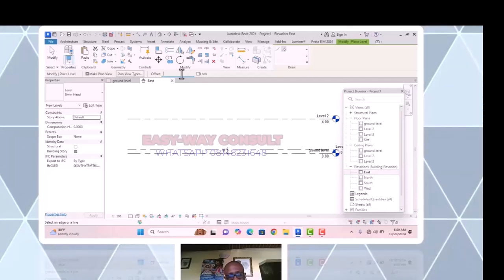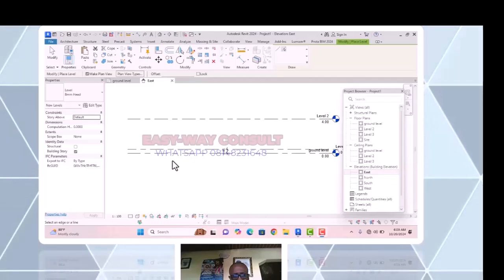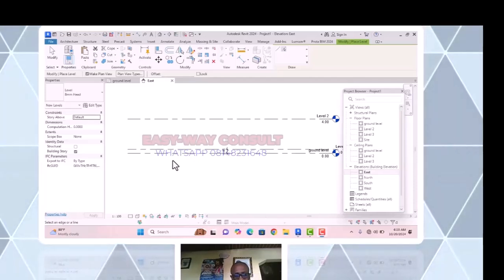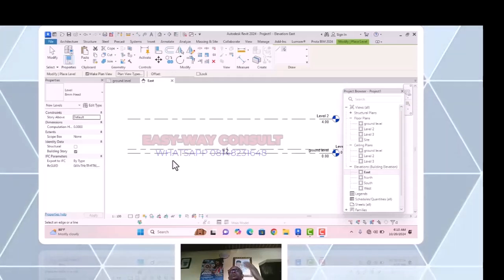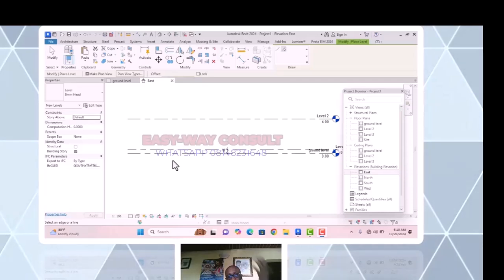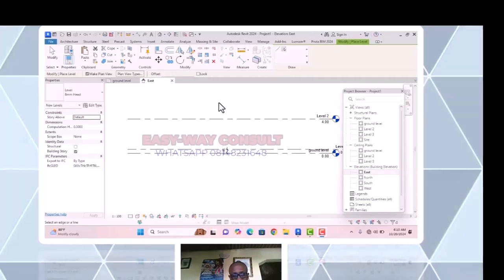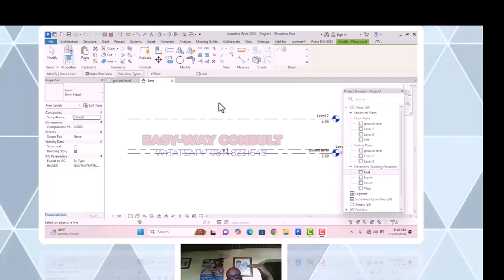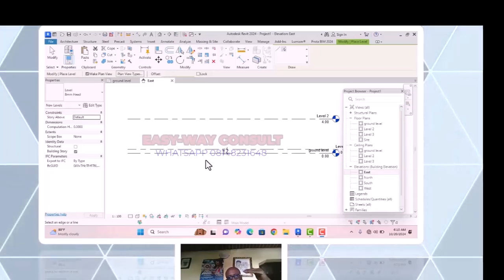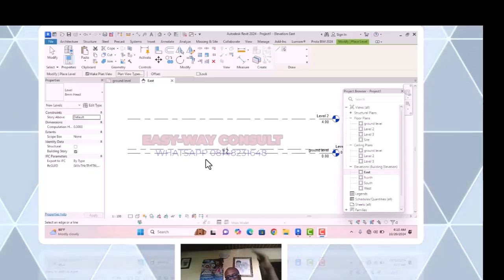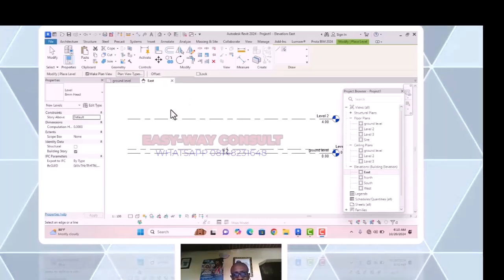Why we are putting 3.6 meter in this ground floor is because most of the time, it is going to be difficult for you to put ceiling, POP, and the rest in your building when you put 3 meters. So most of the time when it comes to deck, we make it 3.6. So 0.6 we take that of the POP and ceiling and it will automatically land the height of your building to 3.00. As the standard of building, we know it is 3.00. So most of the time we don't go through that 3.00. We make it